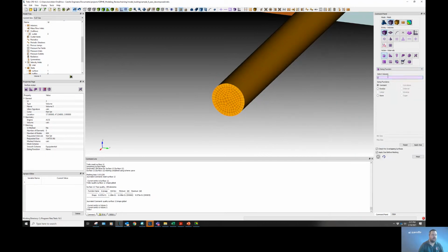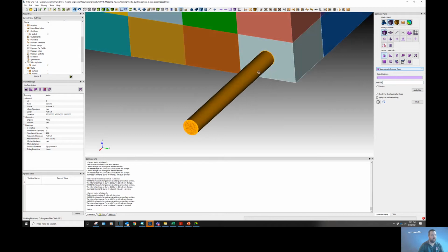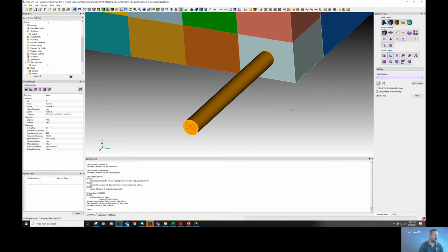So we'll want to use a sizing function or set the approximate number of elements on this face. If it's 15 feet long and we're using 3-inch or finer, we end up with approximately 70 elements. Define the mesh on the face with a map.